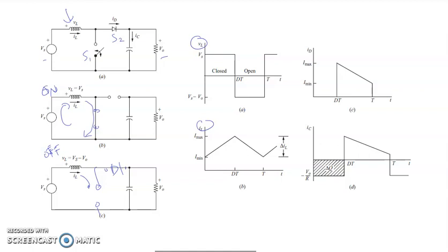When the diode is forward biased, we consider it a short circuit, ideal. By right we have a voltage drop, but we consider it ideal, so there is no voltage drop. So the circuit is fully connected. It flows through the diode, to the load, and back to the source.